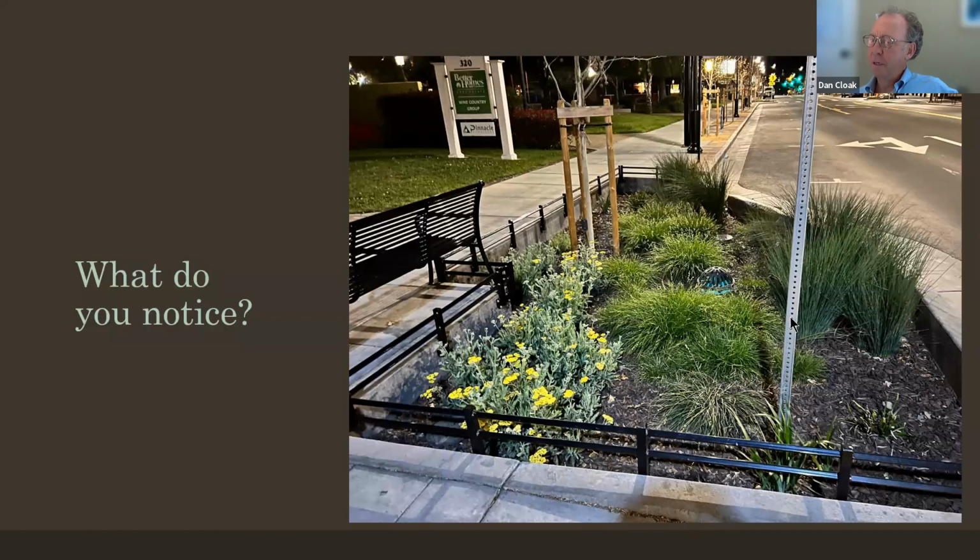Often the reason this happens is something that could have been avoided with planning, particularly when you have this on a site where you've got more options, on a parcel rather than on the street. It could have been avoided to have part of your bioretention facility taken up with the basic foundation or concrete base for a street sign.